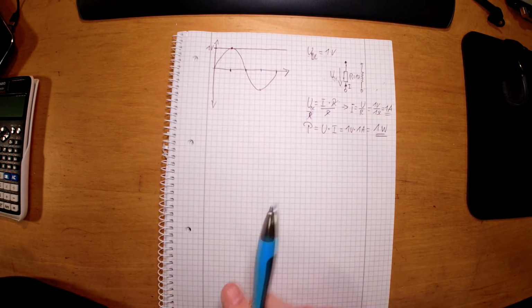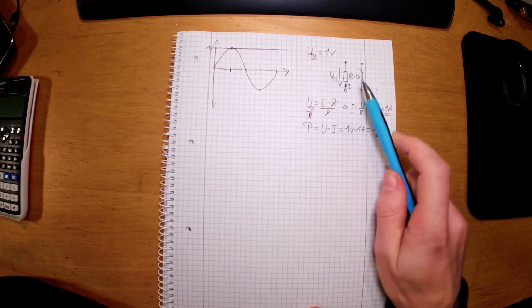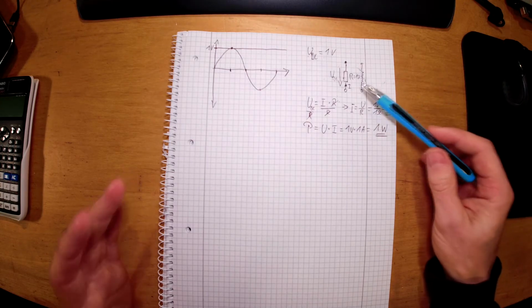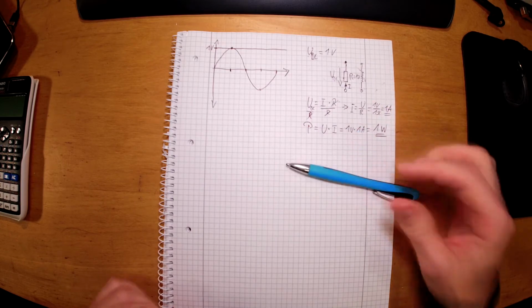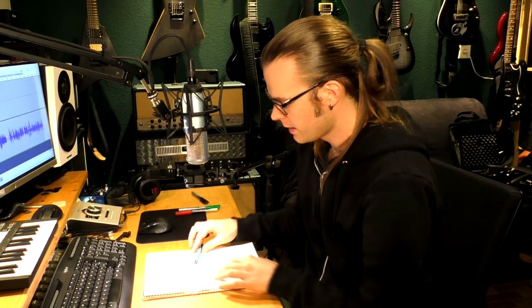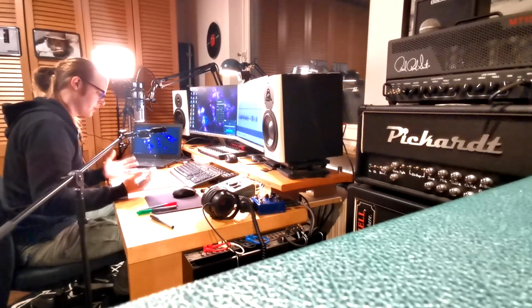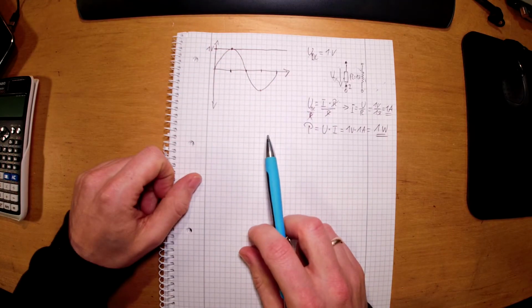Okay, now the question is, think about this resistor and think about a power amplifier. We know resistances, they are a bit higher in our usage. They are like on a normal speaker 4 or 8 ohm or 16 ohm for guitar speakers mostly. And we want to know how much power our amp is putting out maximum without distortion, for example.